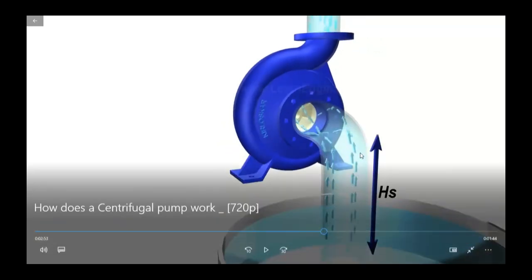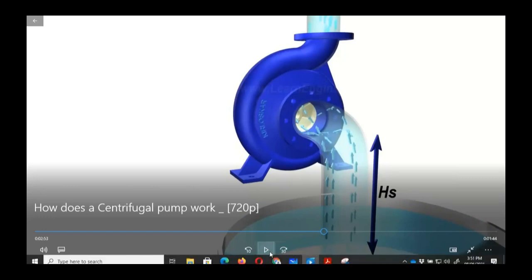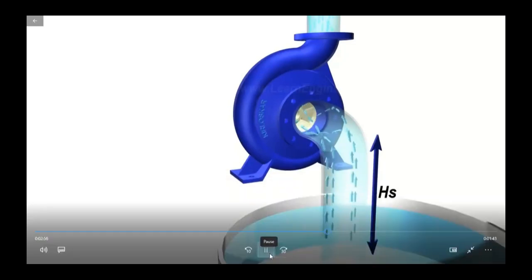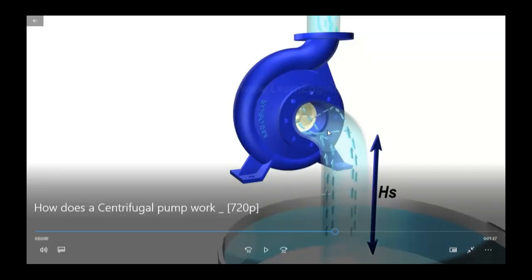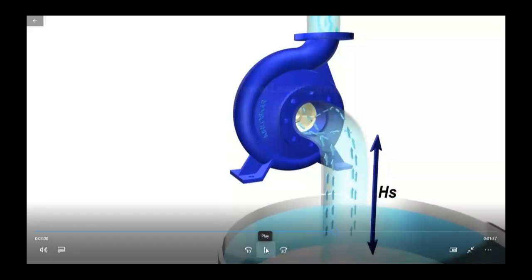Okay, so the more the suction head, the lesser would be the. So it means that we cannot have the pump placed very high compared to the underground tank. Otherwise this value would be very high, and we would need very low pressure in order to tap the water. So that head, which is needed for operation without cavitation, is called net positive suction head.